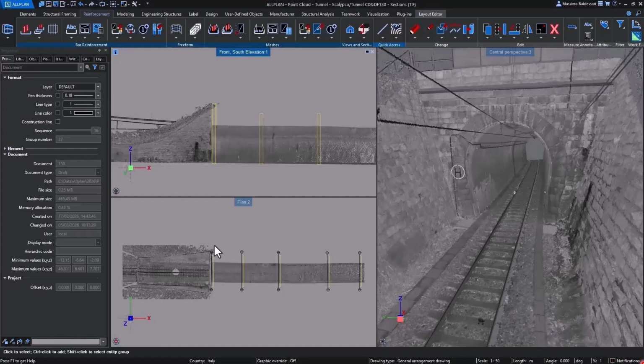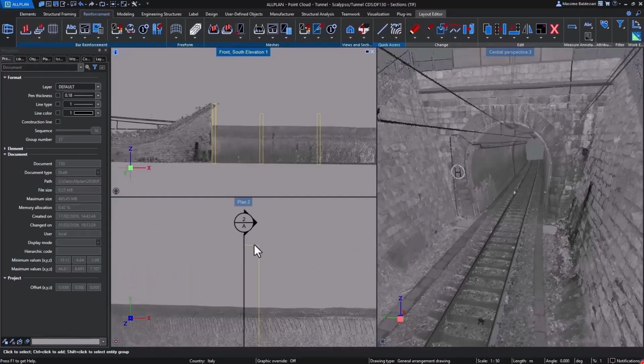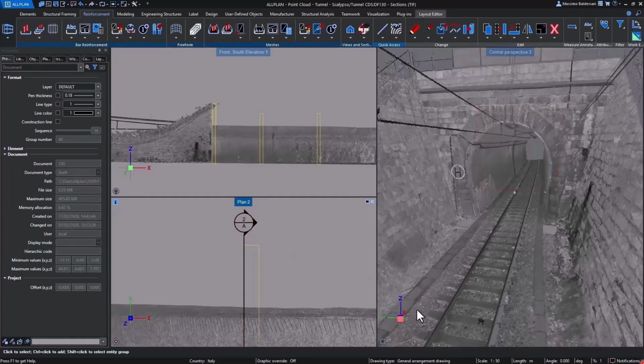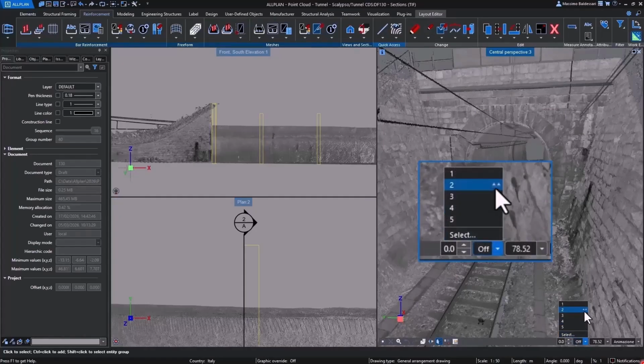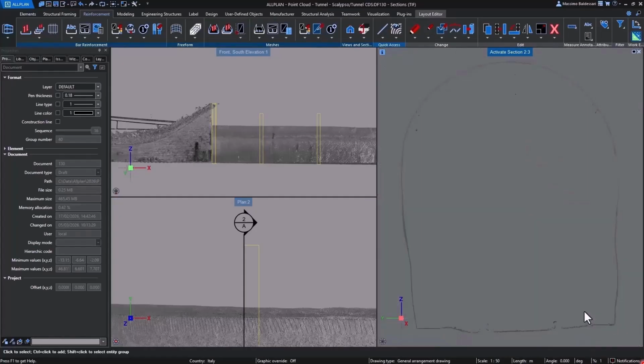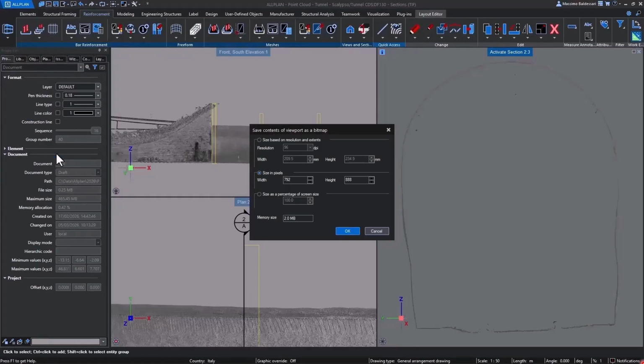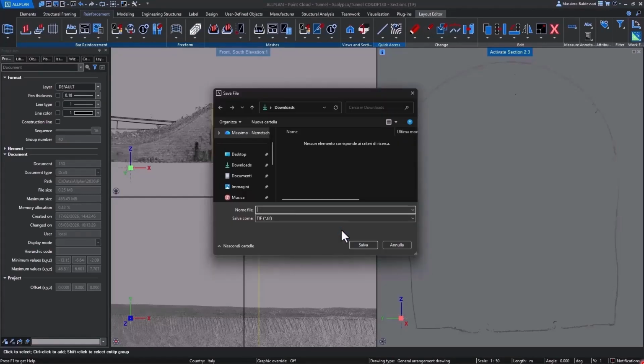That's why you see it in black and white mode. Subsequently, once I have successfully generated my proxy objects directly within the Allplan environment, I then went on to create a whole comprehensive series of detailed sections that I can very quickly and easily recall in this specific way. Afterwards, directly from the active animation window, I could save the final result of the window as a high-quality image. This involves possibly adjusting the specific number of pixels I want to use for the output, and once again saving absolutely everything as a professional .tiff file format.